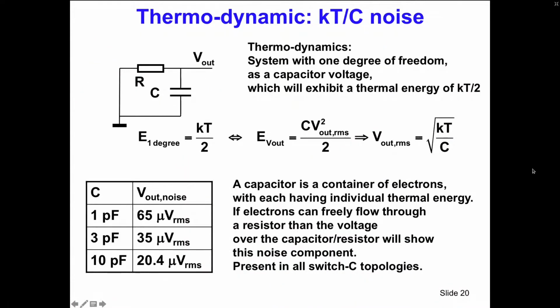Well, noise, kT noise. One of the problems I face with my students is that everybody says, noise, oh, I know that is connected to the resistors. It is 4kTR times the bandwidth, delta f. And I have to tell them that that's rubbish.